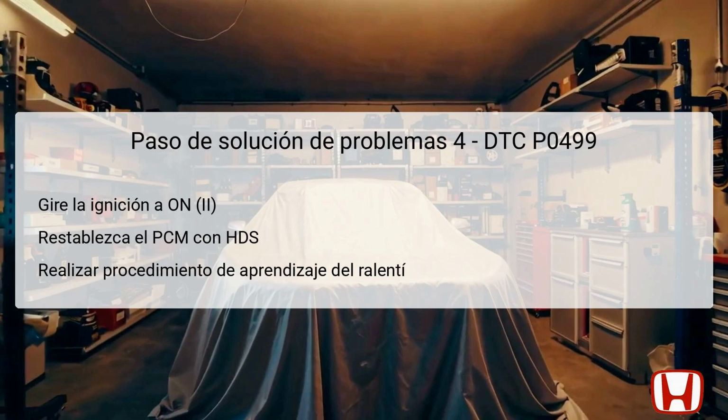After resetting, conduct the PCM idle learn procedure, which is necessary for the module to optimally adjust to the engine's performance parameters. Completing these actions sets the stage for confirming if the issues with the EVAP canister vent shut valve circuit have been indeed resolved.